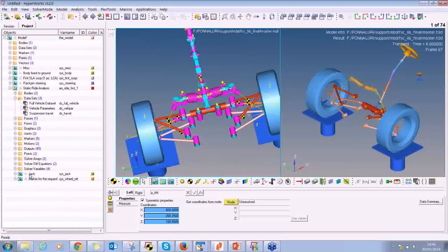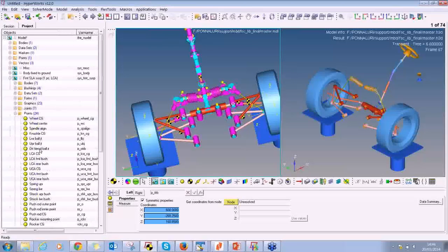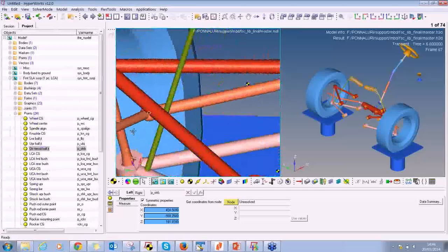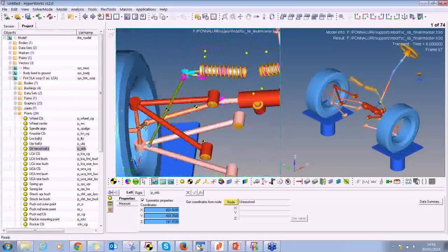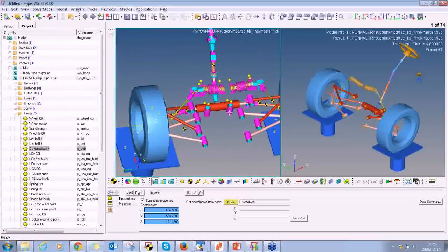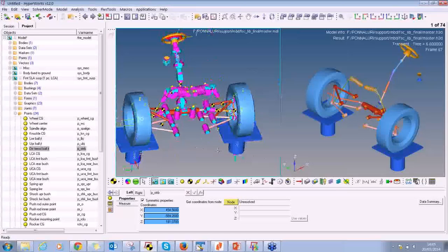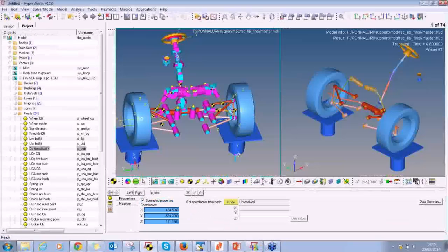and this is the outer tie rod ball joint. Changing the location of this is also going to affect your toe. So these are the 2 points that I will be choosing to vary and study the behavior of my suspension and try to achieve the target curve that I have shown you here.